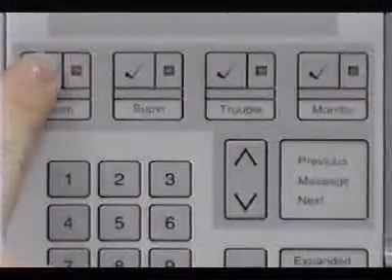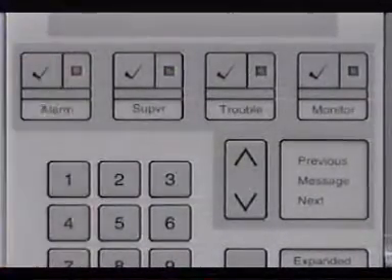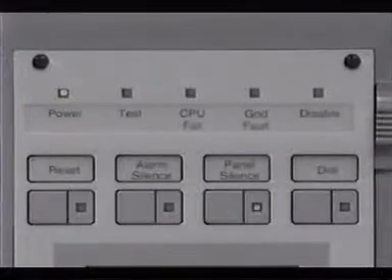An example of an operator's response to an alarm might be: A. Ensure all occupants within the area have been evacuated. B. Notify the fire department. C. After you locate the source of the alarm, acknowledge the message via the alarm queue switch. Then, press the panel silence switch to silence the trouble buzzer.